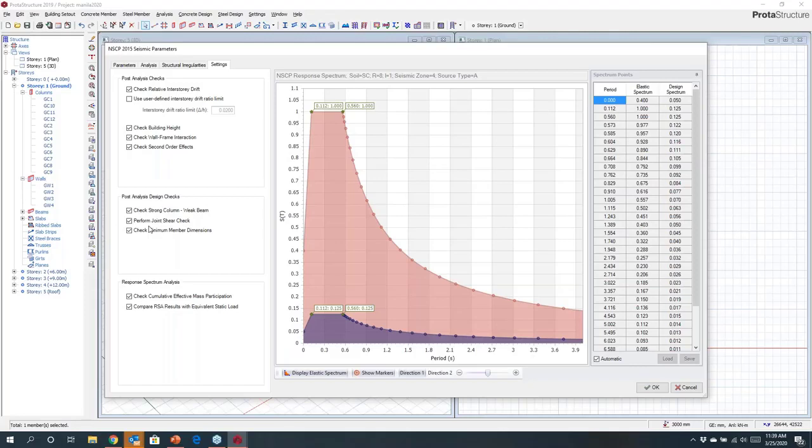Now, obviously, a very important consideration for concrete design, or capacity-based design, is strong column weak beam checks, and we will automate these checks for you. We will look at this floor by floor in different directions, and we will calculate whether a floor in a given direction will satisfy the code. And typically, you need to have at least 70% of the elements in each direction per floor satisfying the code, and we will perform those checks for you as we go through.